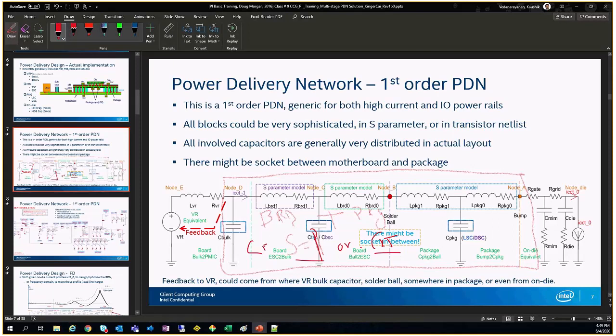So basically this is in the frequency domain. This is your characteristics and this is the time domain. So basically what we do in Power SI is we extract this, and then we convert it into this. Because we have to do two types of analysis, as I would have told you: one is a frequency analysis and one is a time domain analysis. Mostly you will be involved in the time domain. This is where most of the analysis will happen, because generally the frequency domain is just to extract the characteristics, and then we convert it to the time domain and we do it there.